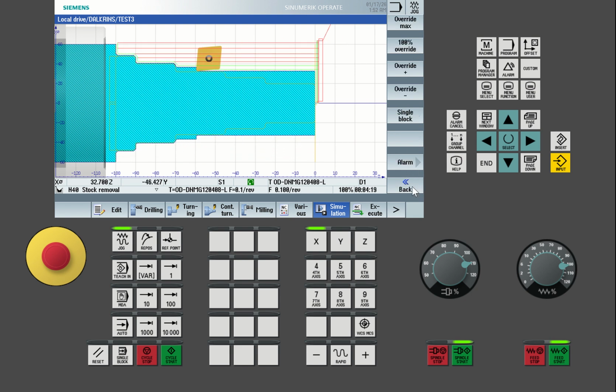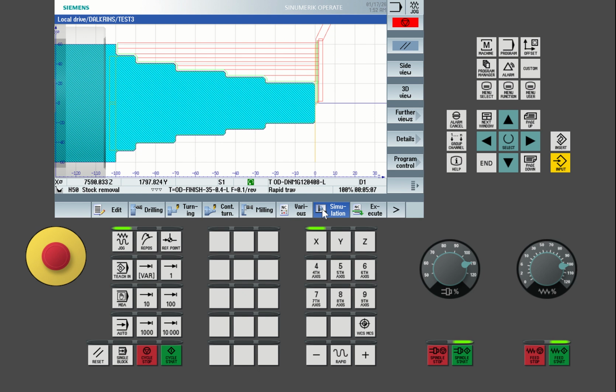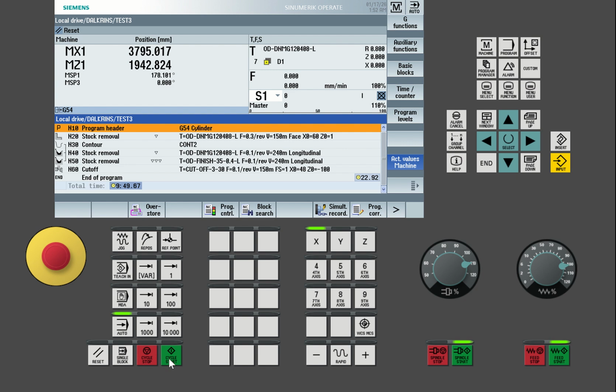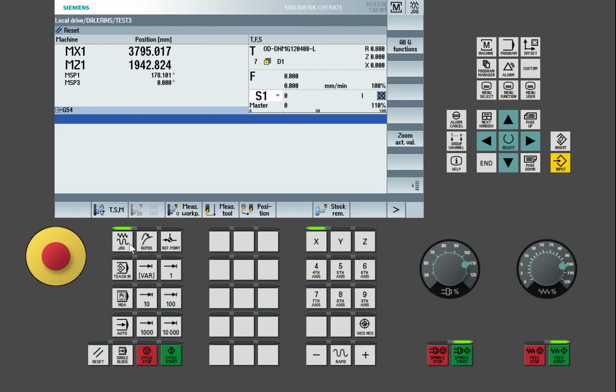You can say overwrite 100% back. Okay. Then from there, once you confirm the program is okay, you do what? Yes, you can now execute the program. Once you see it's okay, then you run cycle start, the program will run. This one is only telling you the point where the machine is. The starting point is not taking place because we have not done the setup. So before you run here, because this is just a simulator, ensure that the setup is okay on all the tools.